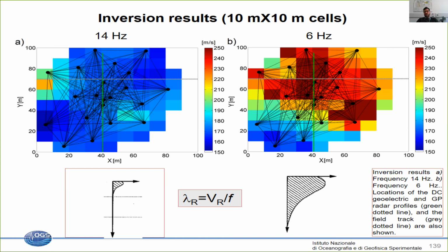So you can select the frequency range where the signal is still strong enough to be observed and you can measure the velocity. It can be that with this distance, when you go to higher frequency, you are not able anymore to estimate the velocity. Or when you go to too low frequency, the wavelength is becoming too large with respect to the dimension of the array. And of course, you will not see the propagation in this method. Everything will be homogeneous. Such a long wavelength will see everything as homogeneous.